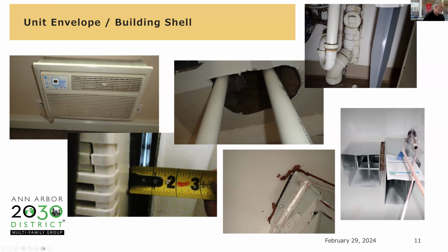And then I see all sorts of weird things. This middle picture in the bottom, they air sealed around all sides except for this foot and a half along the backside here. They could have used the same material. That's a fire stop, and just sealed that up, and it would have been good. Here, this lower right picture, the drywaller got, and this is very common, they don't want to cut a piece of drywall to fit between here. But we need that to be filled. The fibrous insulation is not an air stop. It's not an air barrier.